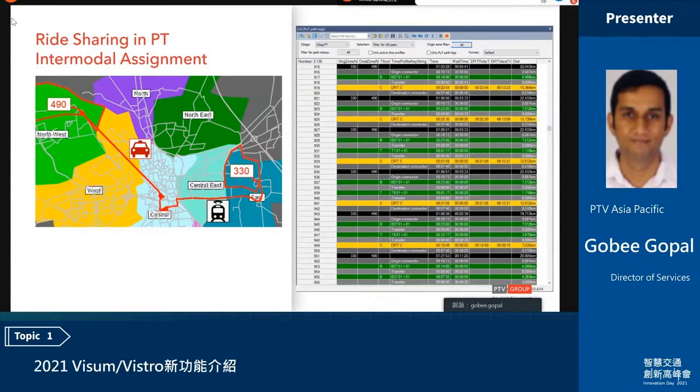The crucial point is that for the route search and route choice, we need travel times of ride sharing links. There's no formula which gives us the value. So we perform a tour planning simulation and derive the travel times from the experienced travel times. To add some stability, we aggregate the experienced detour factor of all realized trips inside a certain main zone relation.